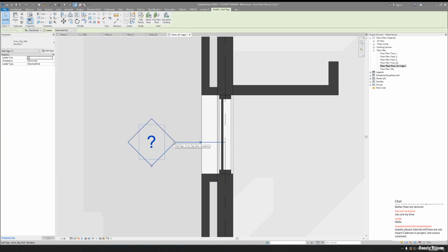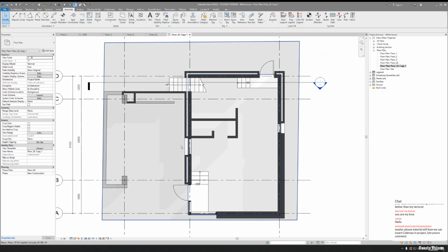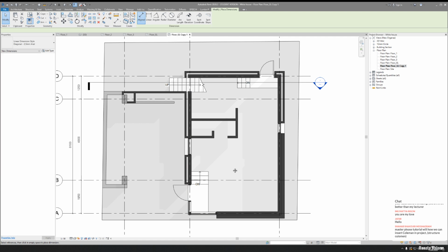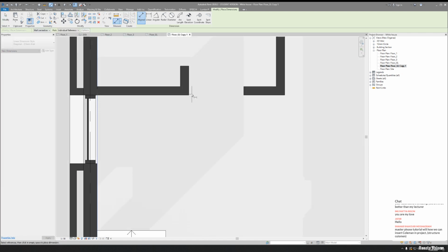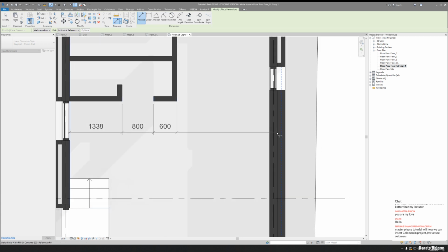So actually this is a huge topic. We should create, for example, shared parameters. We should go to the family. We should create this parameter. We should transfer it to the tag. It really takes time. So if you are interested in it, maybe we will do a tutorial later on, not today, because I would need to spend 1 hour just to explain to you how it works. It's really hard at first, but once you do that, you don't need to do anything manually.